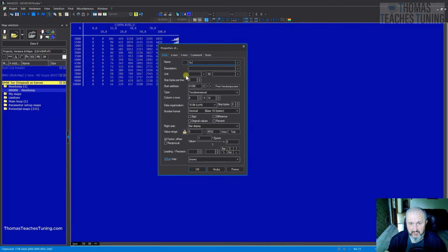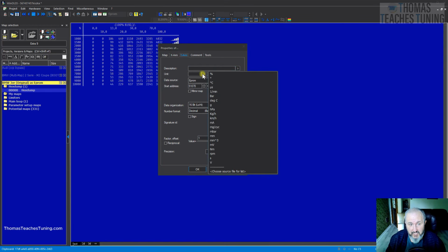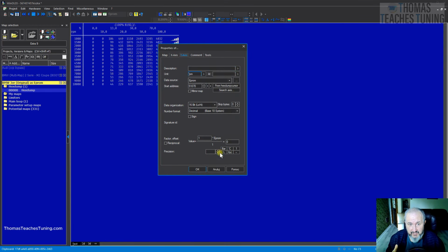Having recalculated the x-axis, let's focus on the y-axis, which represents RPM, revolutions. I noticed that the RPM for EDC17 drivers should be divided by 2, so we need to multiply it by 0.5. So this means divide by 2. We can write this as 0.5 or simply .5 or comma 5, and all the notations are acceptable.